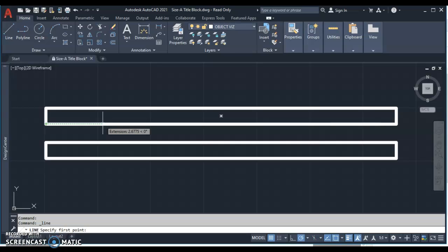and I'm going to put a measurement in. So considering parts E and F, which are 4 inches long, if I extend 4 inches away, I'm going to type the number 4, and I hit enter, my cursor is put 4 inches away from that end point. And now I can just simply draw a line until I reach that intersection there. And I'll click, and then hit escape, ESC. Now I have my first 4 inch part.